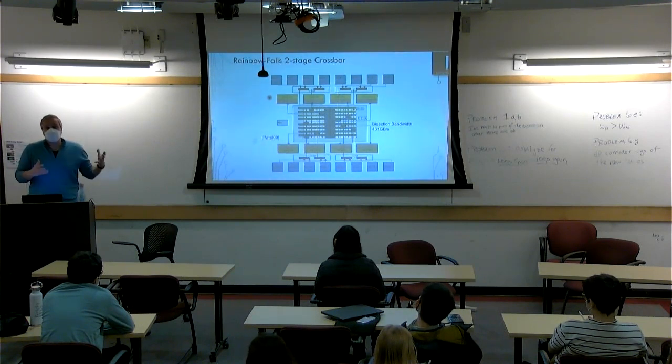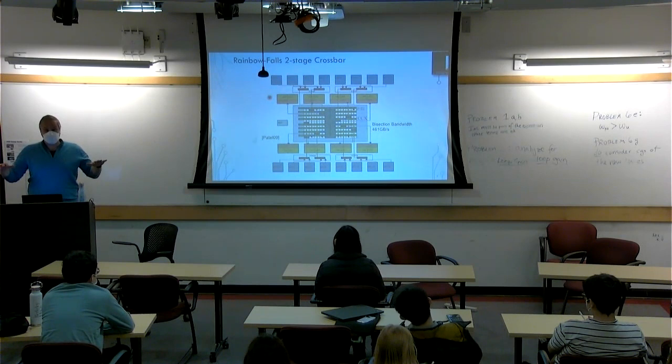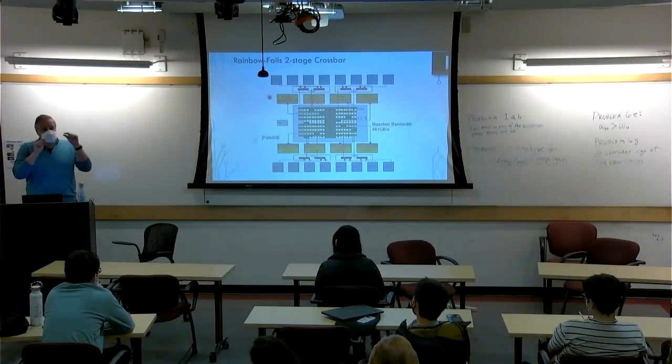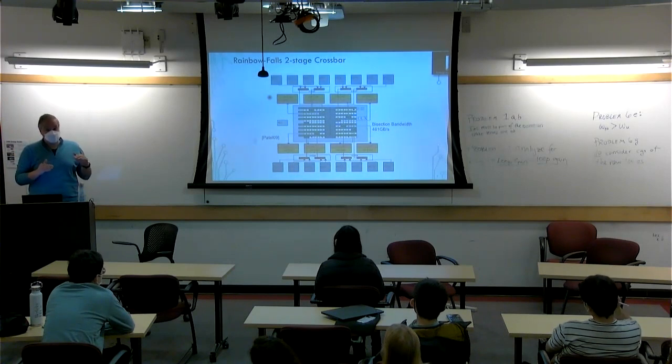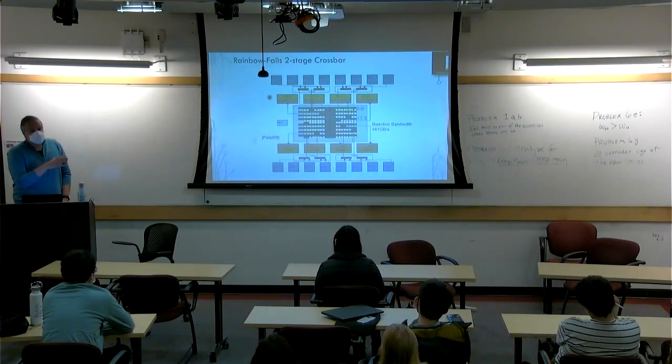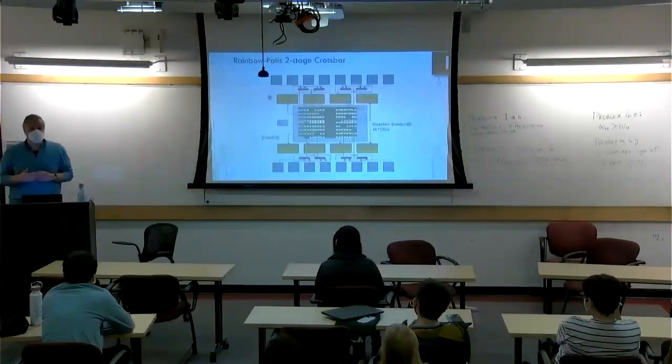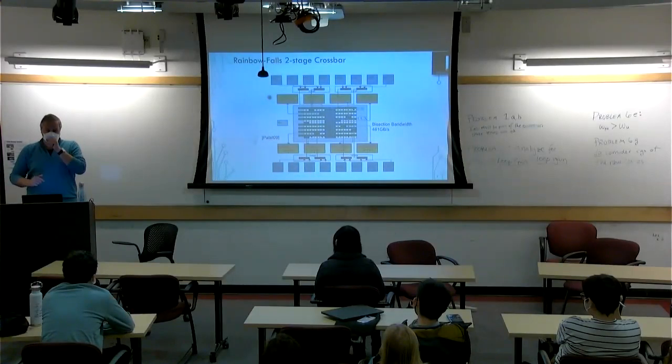And there's really no software running here. It's all hardened essentially in the hardware itself, right? Because it needs to be very power efficient and very fast. So it's very important to look at all these overheads and try to shave them off as you're doing stuff. In these types of networks, a radix 16 router is really 16, you'll see later some examples, 18, 20, but not like 64 or 128. Those crossbars are very big routers, and people build them really for networking fabrics in the backbone of the data center, right? Because they can afford to have big chips with lots of latency and things like that.